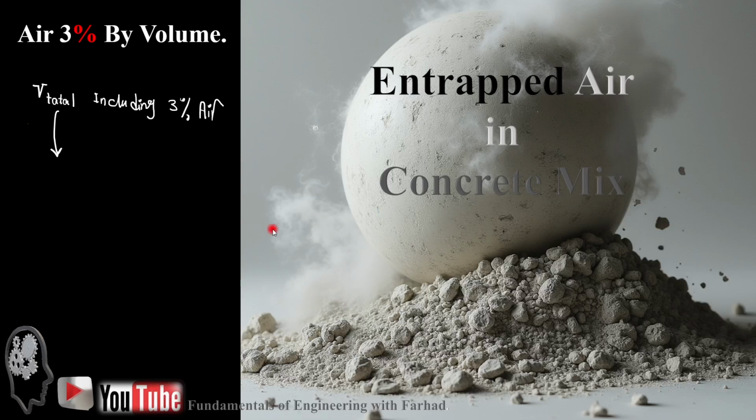And by considering the entrapped air, calculating V total again, but this time including the 3% of air by volume, simply divide your calculated V total by 0.97, which includes the 3% air volume, and it increases the total volume of the material including the air, turning it to 3.766 cubic feet.